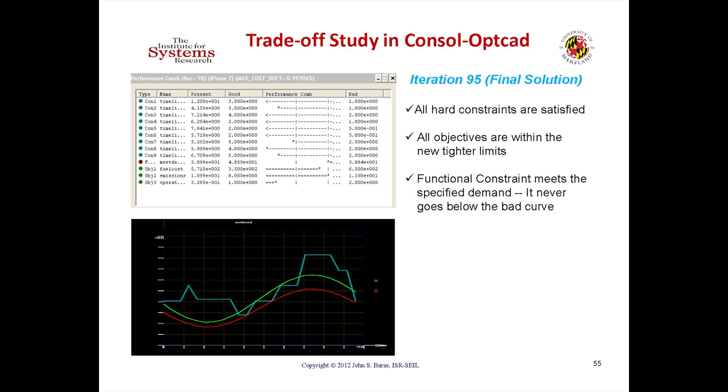How many times? Can you weight those objectives? So, yes, one is more important than the other, or the other is less. You can, but I wouldn't do that. Because unless you have a wise guy that's going to give you the weights that you trust, I won't do that. Because the theory is that if I do trade-off analysis, as you know, and I get the Pareto curve, these weights are the perpendicular to the tangent. So if you're going to do that, do it at least for a range of weights so that you understand the sensitivities. Don't do it just by a single weight.